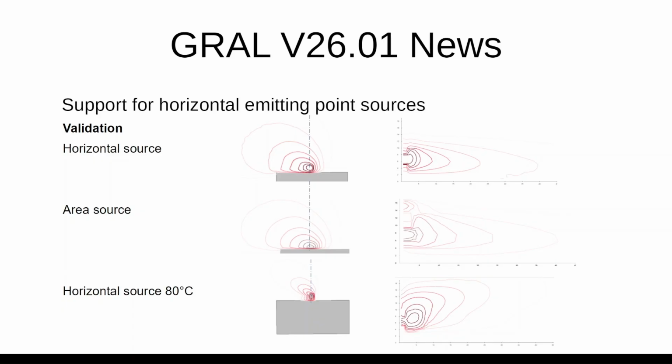The horizontal source is located at a height of 6 meters on the north facade of a 12-meter high building. The outlet velocity is 7 meters per second, the source diameter 0.2 meter, the exit direction 180 degrees, and the exit temperature is equivalent to the ambient temperature. There's a gentle breeze blowing at 0.5 meters per second from the southeast. The concentration is evaluated at a height of 6 meters above ground level. The section extends vertically from the source in the northerly direction.